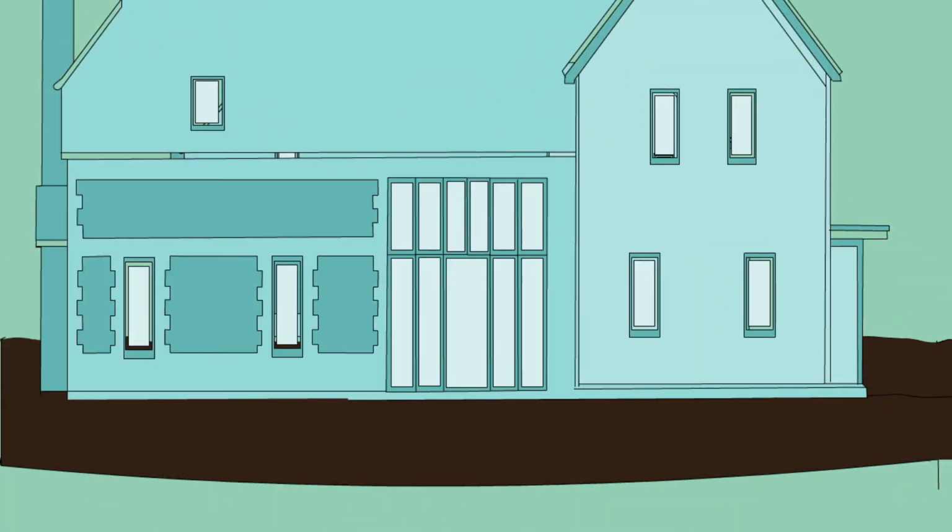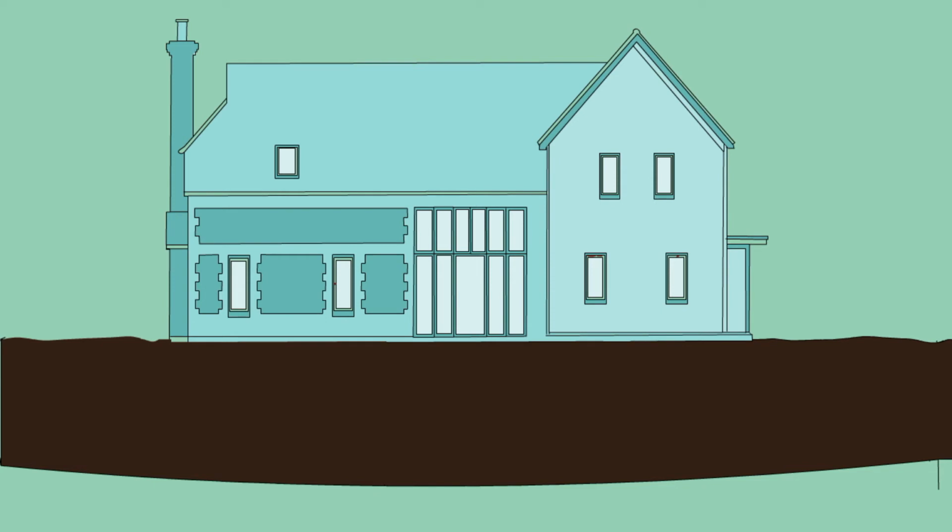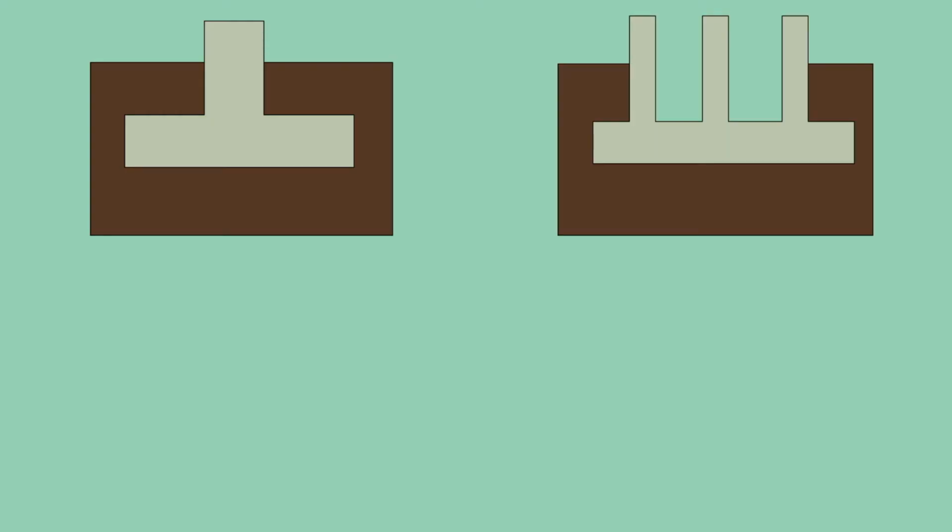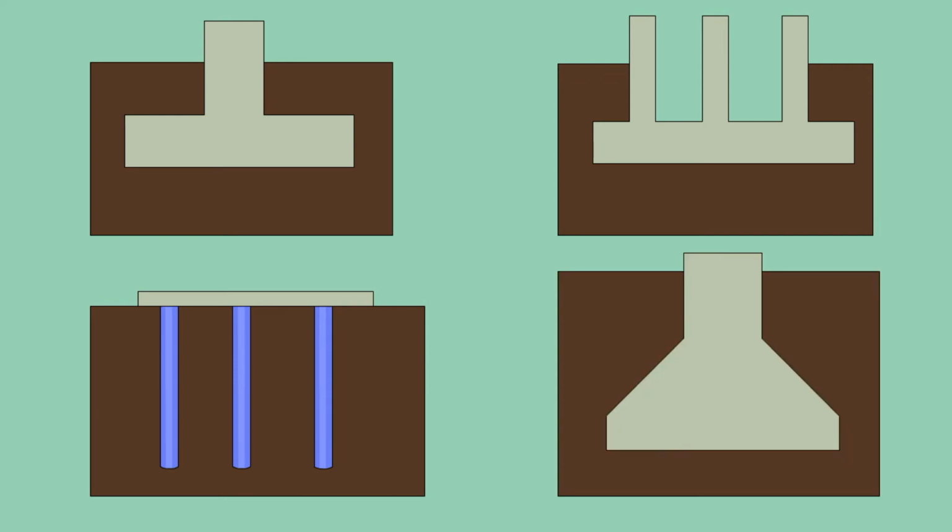Before we dive deep into bearing capacity, we should discuss the types of foundation. Foundation type is based on several factors such as house design, geotechnical location and climate, soil and moisture conditions, and also the project budget. But chances are your house or building has or will have one of these four foundations: spread footing, mat foundation, pile foundation, or drilled shaft foundation. Spread footing and mat foundations are generally referred to as shallow foundations, whereas pile and drilled shaft foundations are classified as deep foundations.